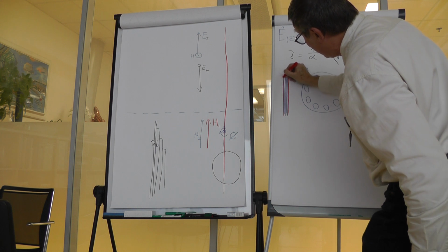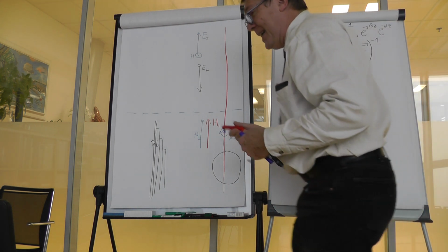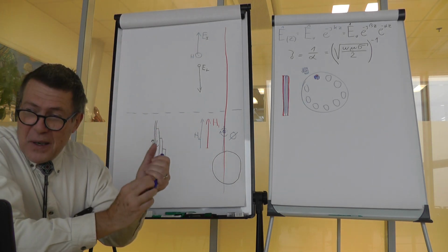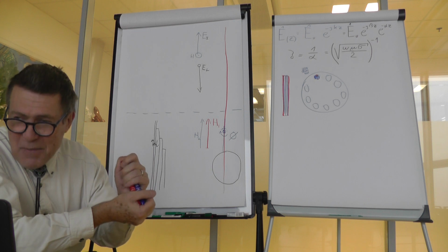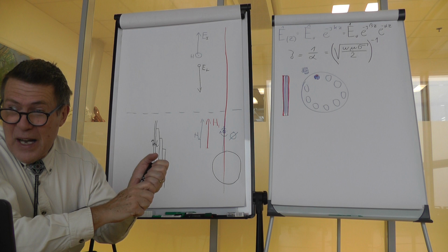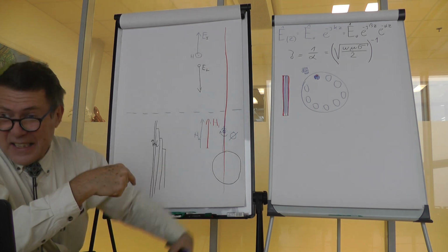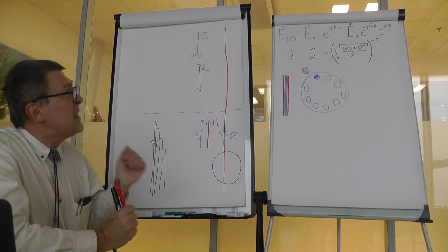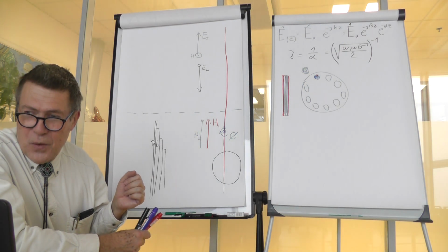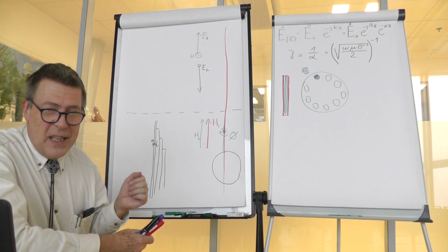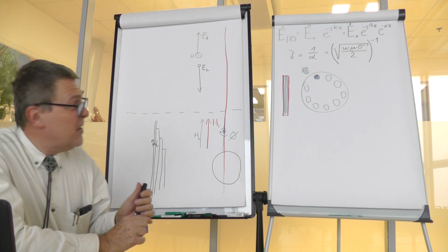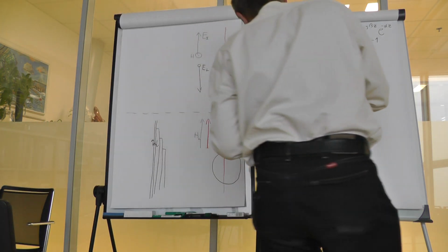This should have been one conductor, from the aim of the designer, but it is constructed from a set of parallel conductors which do not have the same location against the magnetic field, and therefore you could easily get 1 kiloampere of current just running inside it and heating that. To prevent that, a more sophisticated way is used, which is called permuted conductors, and more or less you have a rectangular conductor and a specific prescription.